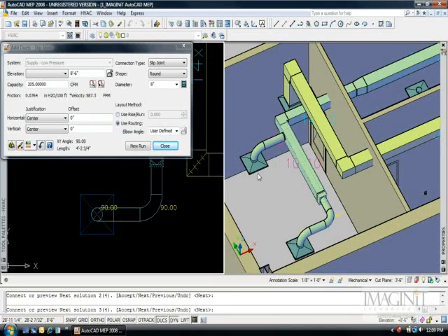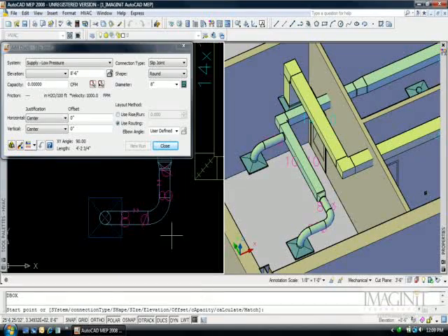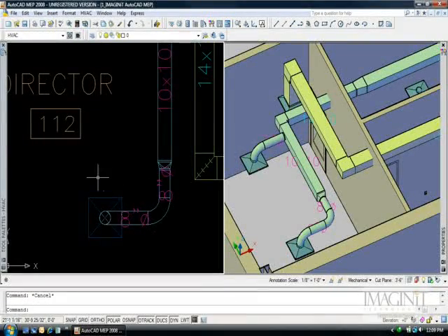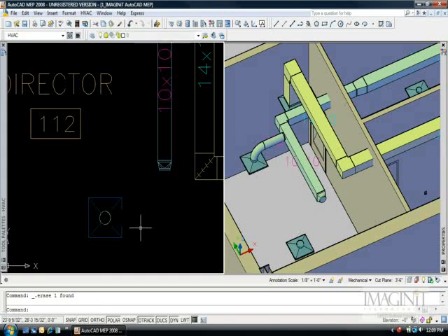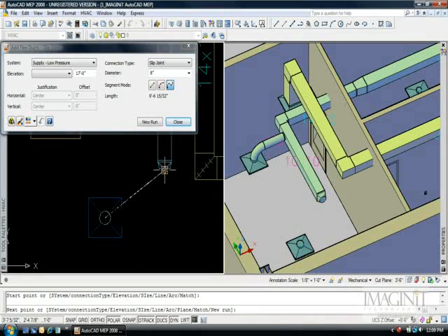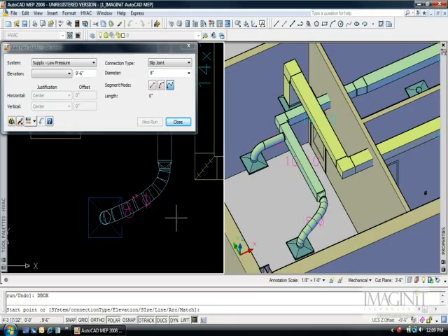I believe I would use this 90-degree one, and once I hit A to accept it, it has created this geometry for me. However, I can have this create different conditions, as not only can I use rigid duct, but I can use flex duct as well. If I select this and simply hold Control when I place the Add Duct tool, once I connect in, you can see that I have now connected this with flexible duct.